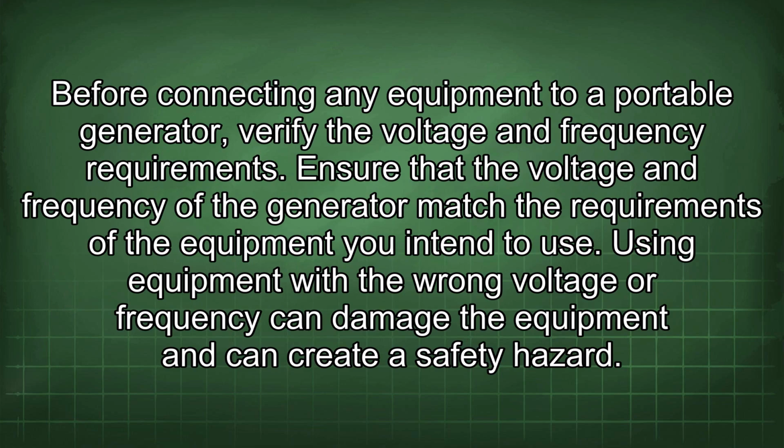Before connecting any equipment to a portable generator, verify the voltage and frequency requirements. Ensure that the voltage and frequency of the generator match the requirements of the equipment you intend to use. Using equipment with the wrong voltage or frequency can damage the equipment and can create a safety hazard.